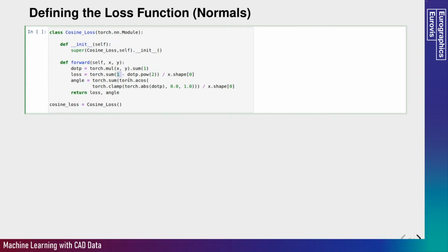Instead, we are taking the second power of the dot product. This power function changes the sign of the dot product, so normals pointing in opposite directions are considered as pointing in the same direction. In other words, we're mapping the normals from the full sphere into a half sphere, and by doing this we're basically ignoring the direction of the normal.